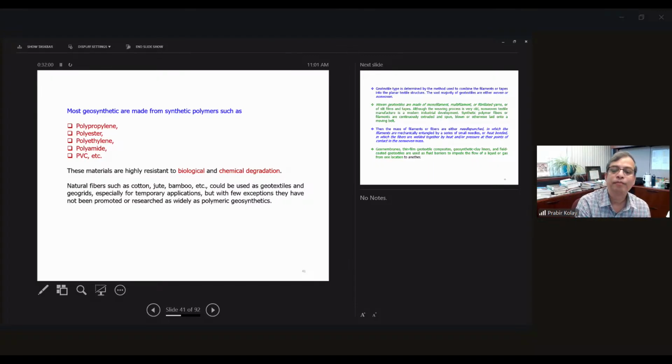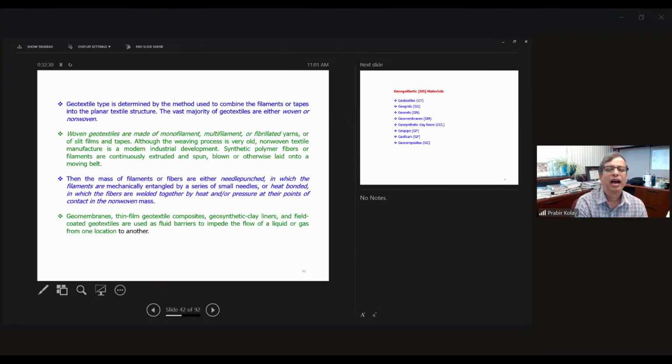or material. So we need to see, although the problem is if you insert the steel, there is a problem with corrosion. If you insert that geogrid or geotextile, it is not going to corrode, but there will be deterioration due to the UV light.